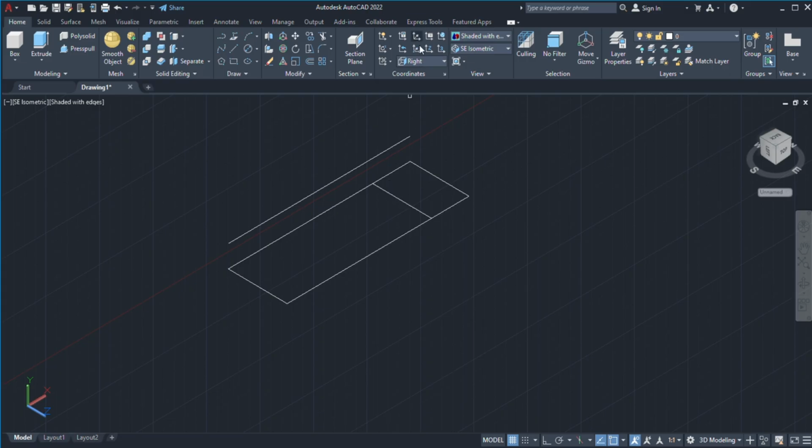So it is not shifting because we are not in there. We are offsetting in the wrong plane. Shift to the front plane. Offset the 20. Enter. So having done that, we have a center point for a circle, or let's say for some circles.